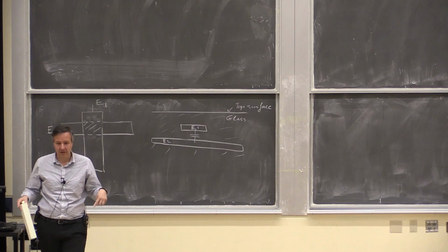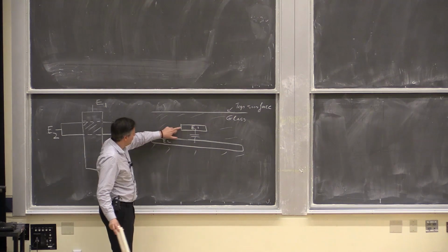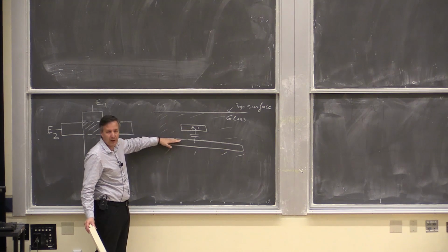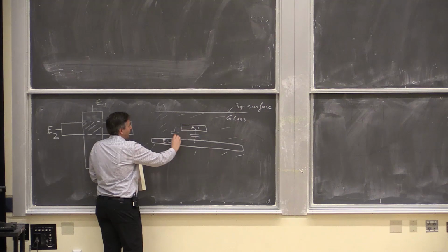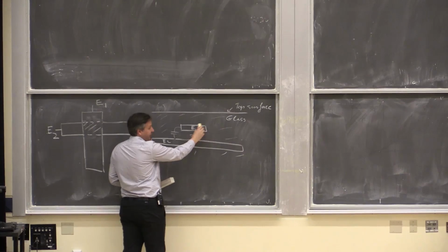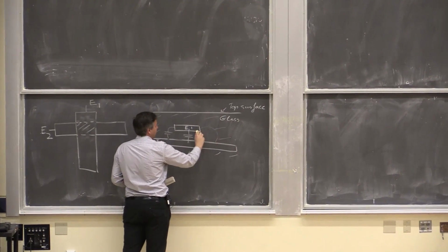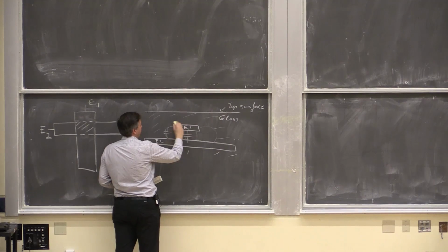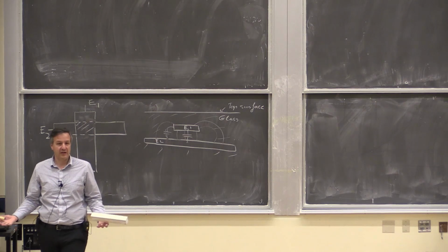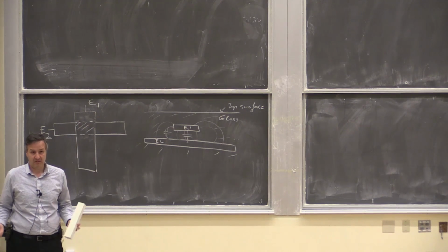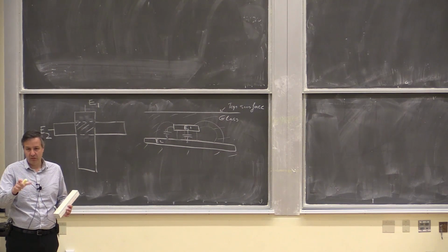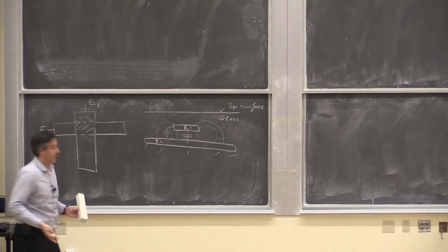In reality, people who have done some physics will know that each part of the conductor actually terminates the field. It's not just the bottom plate. So even this side would have some fringe capacitance to this metal. It would go something like this, because if I draw the electric field lines that go out of this, if I was to put charge, the field lines would be going like this, even a little bit from here. Wherever the field lines go, there is effectively a plate. But for all intents and purposes here, we're just going to assume the wire is wide enough that the bottom plate dominates.